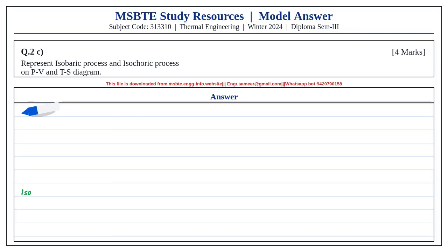According to construction, they are tubular, shell and tube, plate type and extended surface type. According to direction of fluid flow, they are parallel flow, counter flow and cross flow. According to pass arrangement, they are single pass and multi-pass. According to physical state, they are condensers and evaporators.